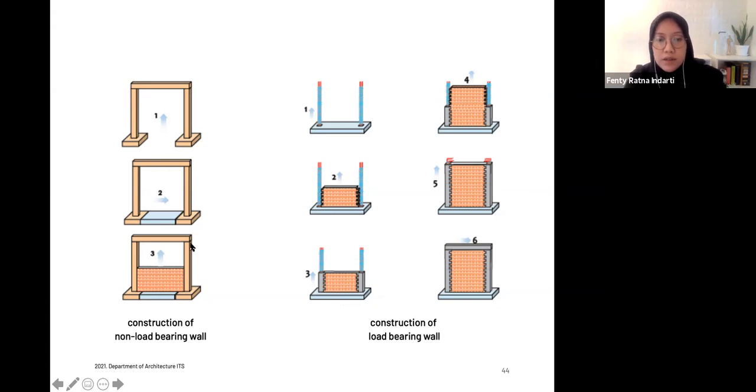Imagine with this type of wall, you have a lateral force, like shaking. Like I mentioned before, if you get a lateral load here, it will collapse, because it doesn't have any type of holder or anchor. While this one, because you build it alongside the structure itself, has anchors, and it will stay in place during the earthquake, so it doesn't create serious damage to the building.